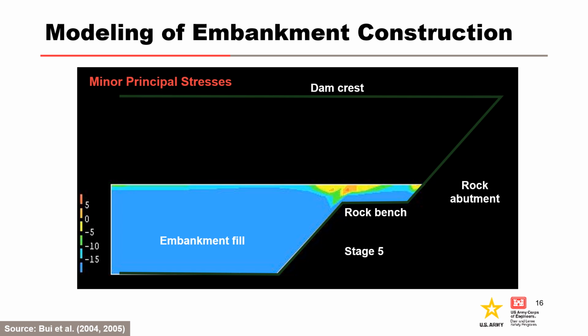Tensile zones develop during the varying stages of embankment construction. This can lead to cracks at depth, but which then close up as additional fill is placed. The following sequence of slides shows the development of minor principal stresses from finite element modeling as an embankment is constructed above a bench in a steep abutment. It should be recognized that these stresses are inevitable, even in well-designed and constructed dams, and are not caused by poor design or construction practice. The following animations progress through the modeling of embankment construction.